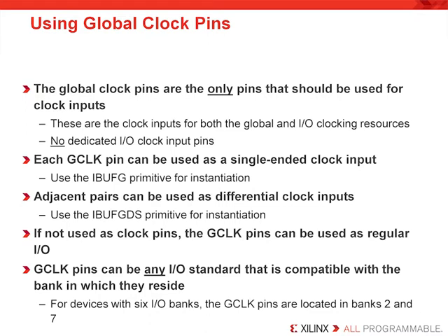As an FYI, if you don't use the dedicated clock pins for clocking, you can use them for regular I/O as well. The pins can support any I/O standard that is compatible with the I/O standards used in the same bank. This is required as part of the I/O banking rules. These rules require that input pins share the same power supply in a single bank, and that output pins share the same power supply in that bank as well.